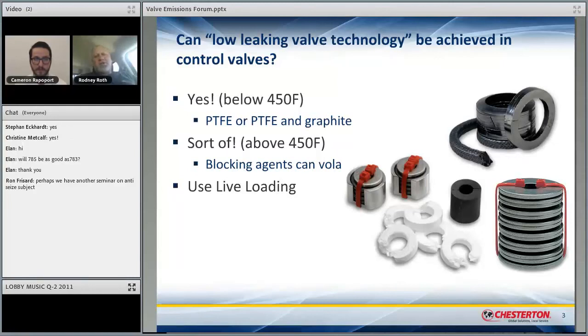And we're working on 641, which is a quarter turn standard for graphite packing as well. And there'll be other standards that come out. We never talk about control valves because people usually follow the ISO standard for that, because it's a valve by valve test, and there's no real industry standard manufacturing protocol for how they make control valves, so it'd be kind of hard to make a test standard.